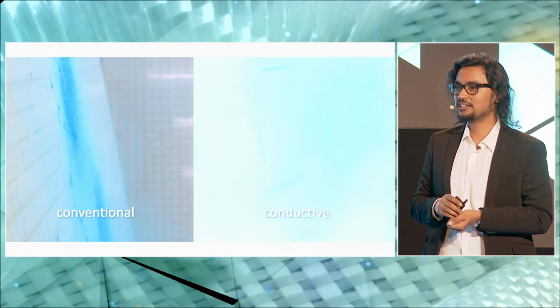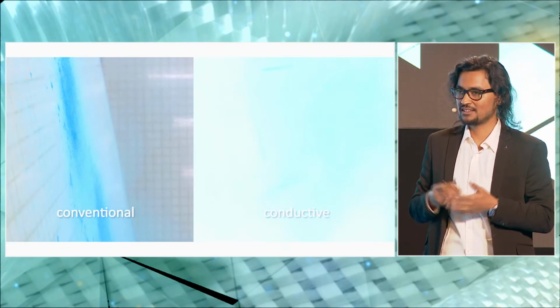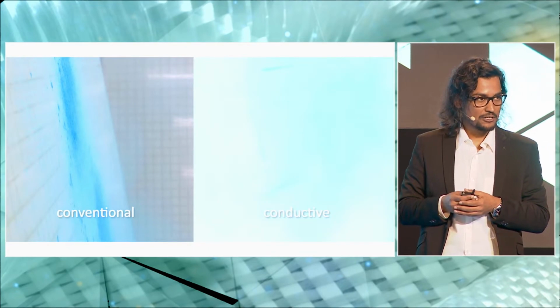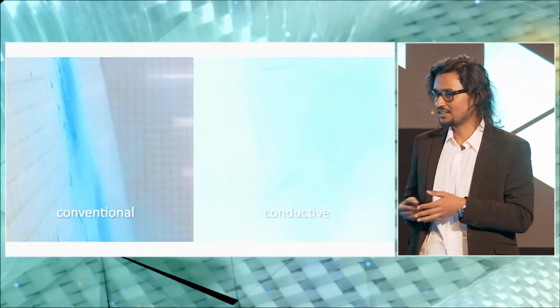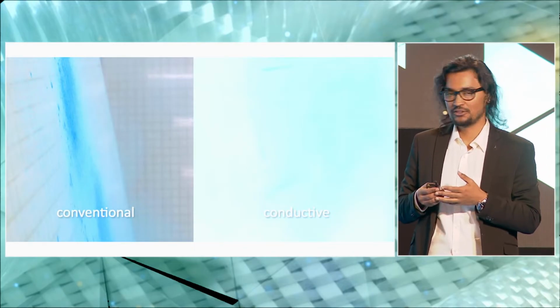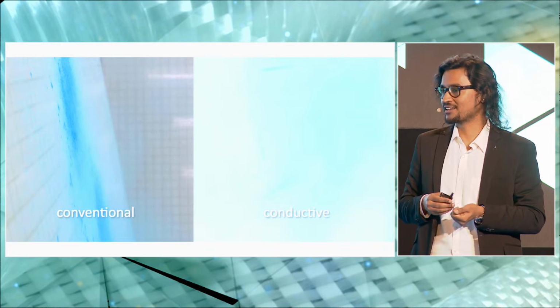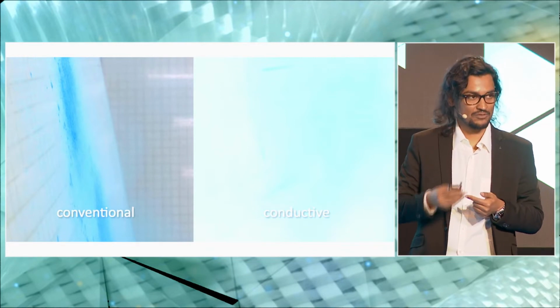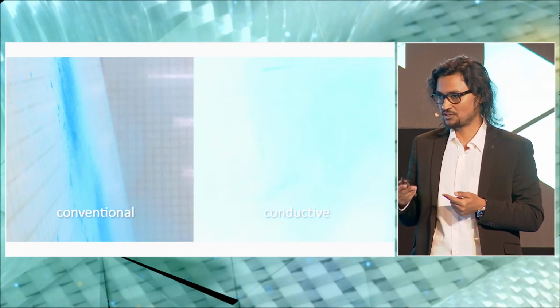after putting nanotubes in the mold coat or gel coat, while opening the mold, there would be no sparks. And as a result of which, the whole process is much more safer. The whole process is also fast. That means faster productivity and safer operations.